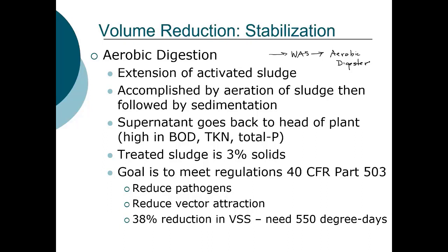That supernatant is highly concentrated. It's got a high concentration of BOD, total Kjeldahl nitrogen, and total phosphorus. And your treated sludge typically has about 3% solids. The goal is to meet the regulations in 40 CFR.